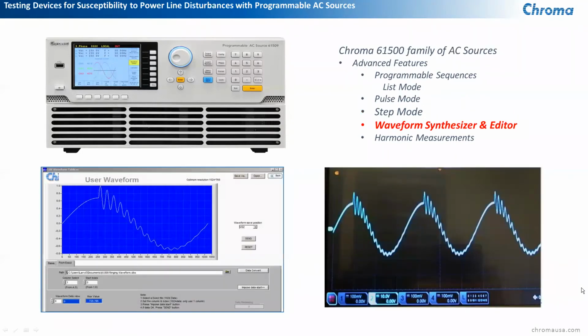Another thing you can do with this is you can embed another waveform on top of this waveform. You can do that through the Excel. Here we did a capacitive ringing circuit test for a customer. And what we did is we took 2 waveforms at 2 different frequencies, and basically we embedded a portion of that waveform into the sine wave by just doing a mathematical add, or we did a macro that would allow it to impose that onto the waveform.